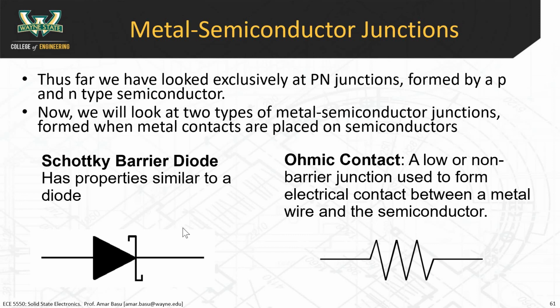Yep. And usually they use the Zener to protect the gate of the MOSFETs, like for any transient voltage. Yes, you can use clamping diodes to protect the gates of MOSFET devices. Yep. Thank you. All right. Good questions. Thank you.